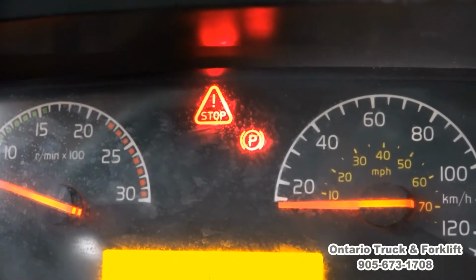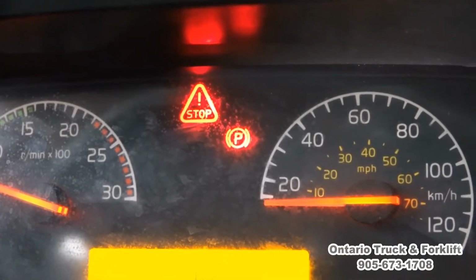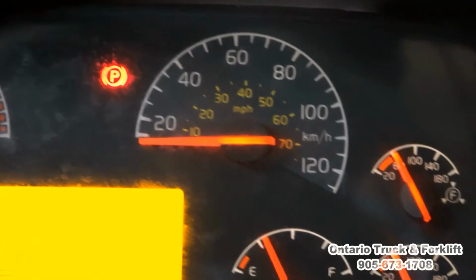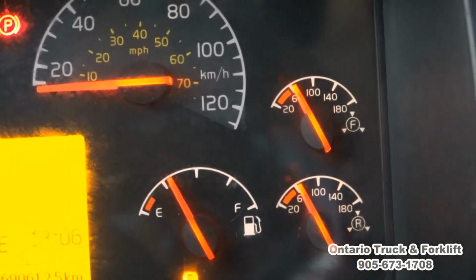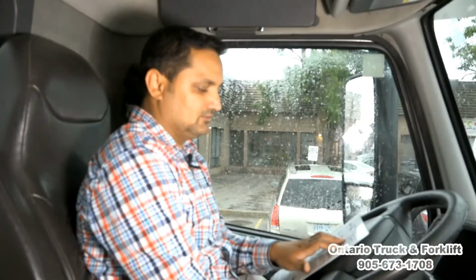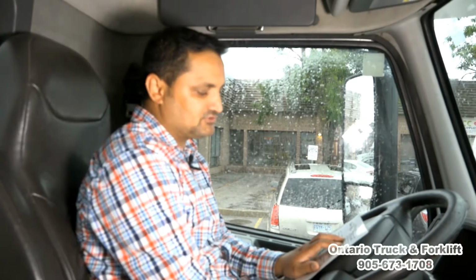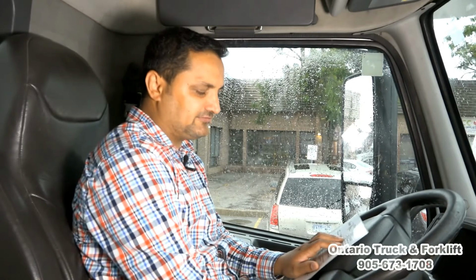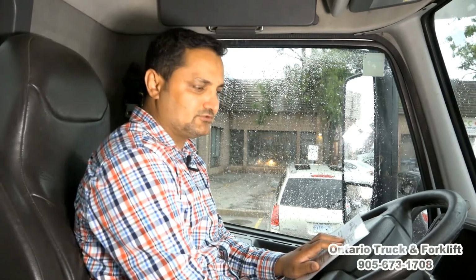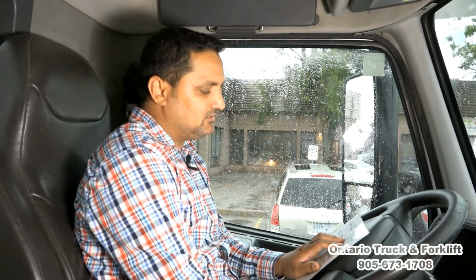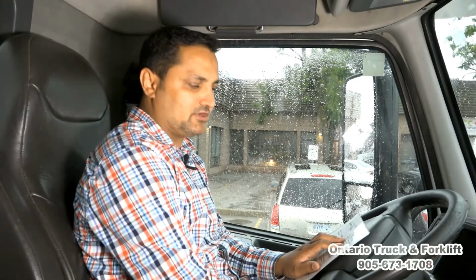Low air warning is working at 55 psi, which is good. If it works below 55, the vehicle is defective. Now we have to read Schedule 1. If the low air warning system fails or is activated, that is a major defect. If we have a major defect in our vehicle, we cannot drive the truck. We have to call our owner, report it in the logbook, and we cannot drive.